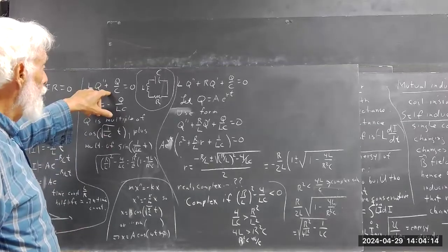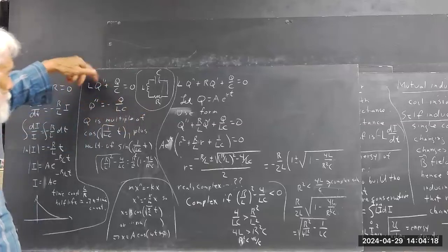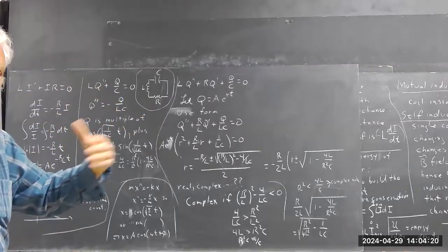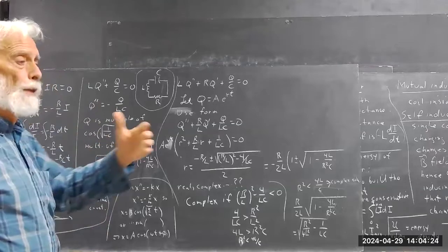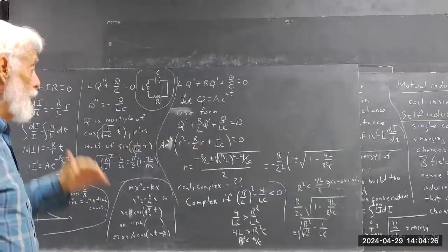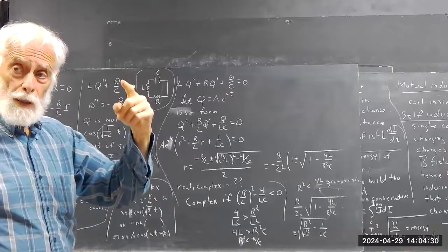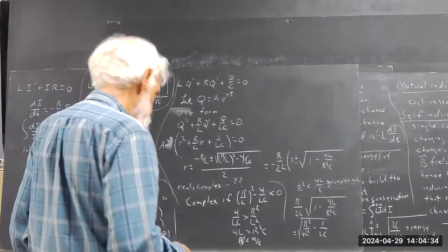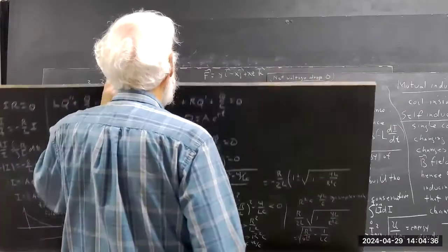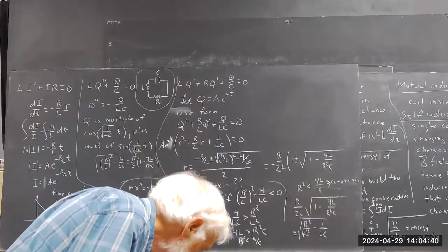Okay. So by inserting an R in here, you now start damping out these oscillations. And the greater R is, the more they damp out. If R gets big enough, they damp out so much that they don't oscillate. Okay, so your oscillations, the board space, hang on a minute.